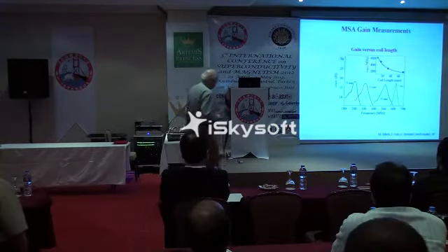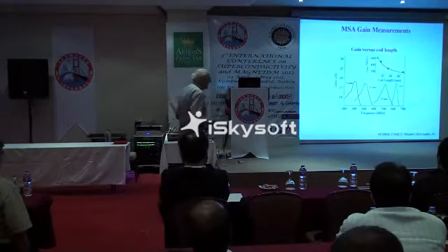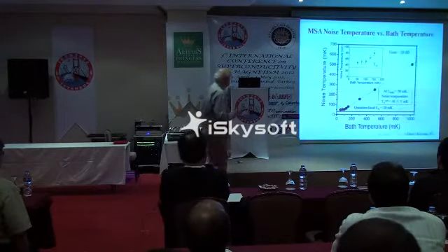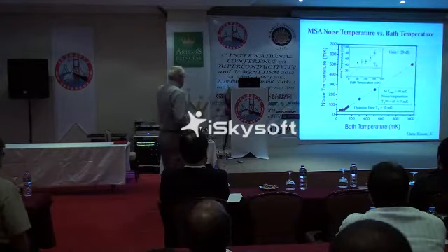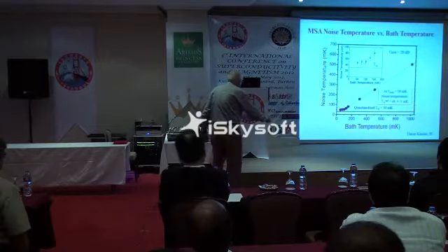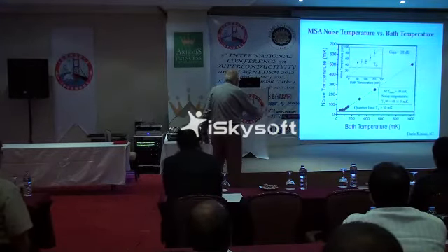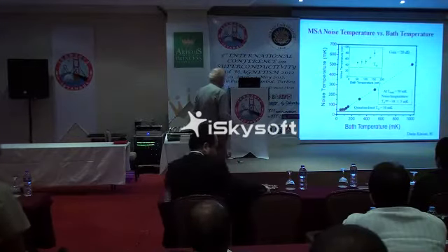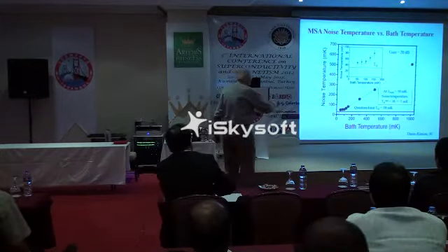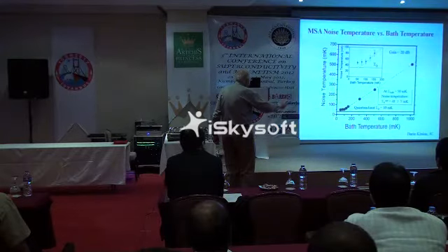Well, we've made various versions of these over quite a few years, and I just want to show the result for the current version that we've made to demonstrate the noise temperature. So along the horizontal axis, I'm plotting the bath temperature of the squid, and along the vertical axis, I'm plotting the measured noise temperature, both in hundreds of millikelvin. What you see is that as we start to decrease the temperature, the noise temperature decreases linearly.